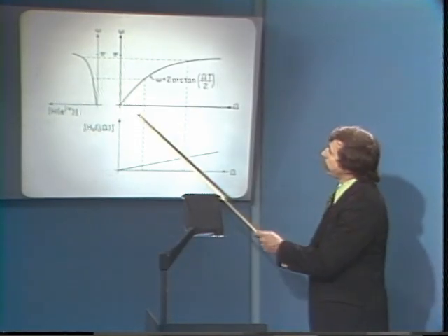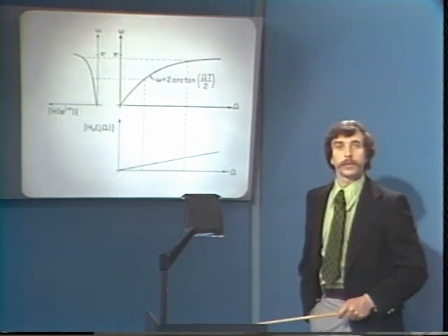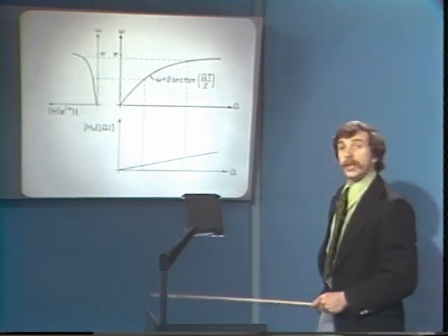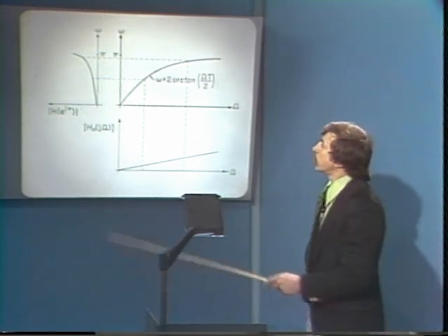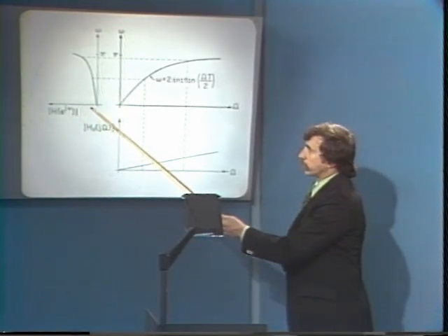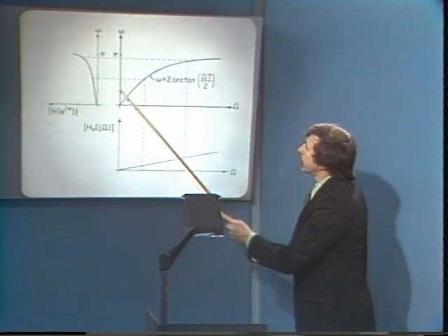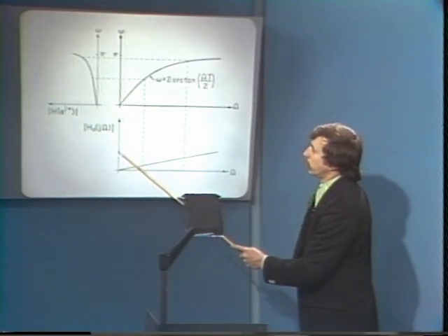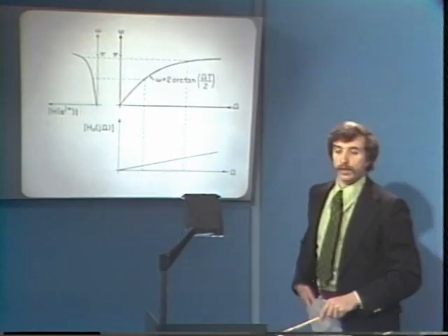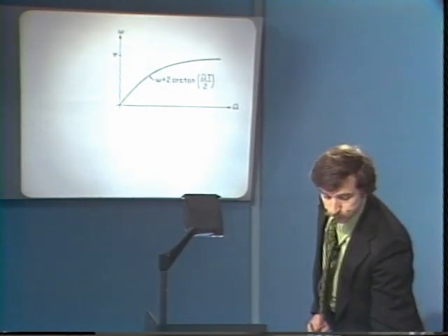Well, where might we be able to tolerate this kind of a nonlinear distortion in the frequency axis? One place we could is when the desired digital filter is piecewise constant, in which case that will get reflected into a piecewise constant analog filter. And let me indicate that more explicitly.